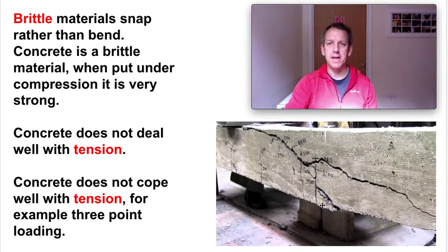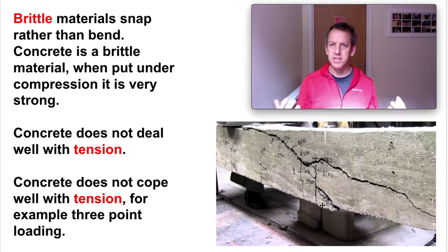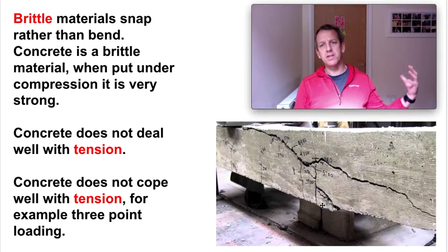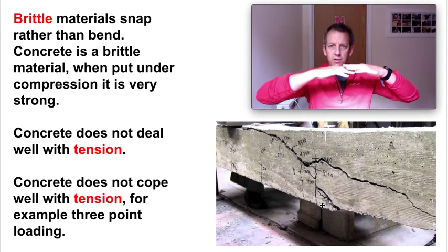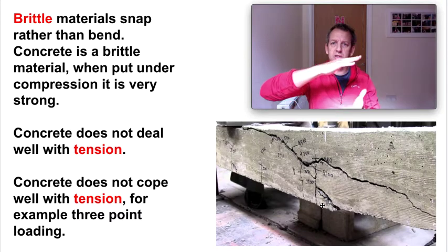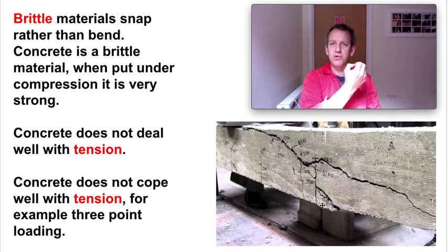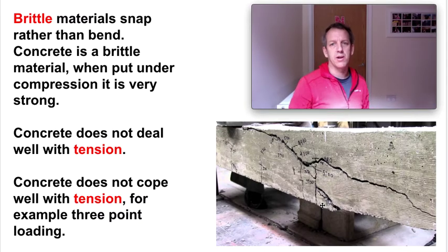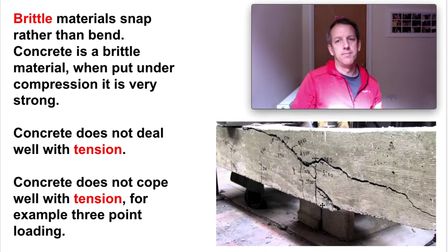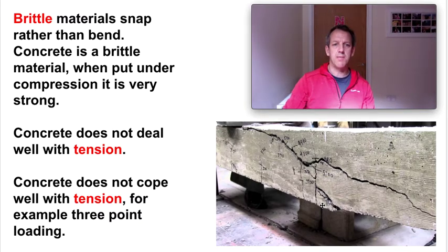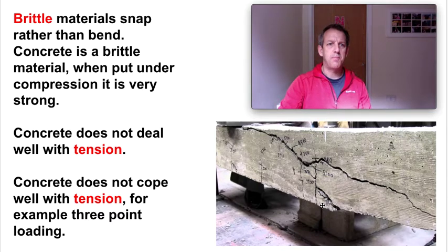So if you had a timber beam or something like that, where would you expect to see the splinters? You can quite often see this in your house. If you look up at the ceiling downstairs, if you've got a plasterboard ceiling, and if you've got flexy timber joists and they flex too much, it will start to push the nails or the screws that hold the plasterboard in place out, and you'll start to see cracks appearing in your house. It's not a problem, and we can have a certain amount of flex in our houses. We'll come to that in a bit.